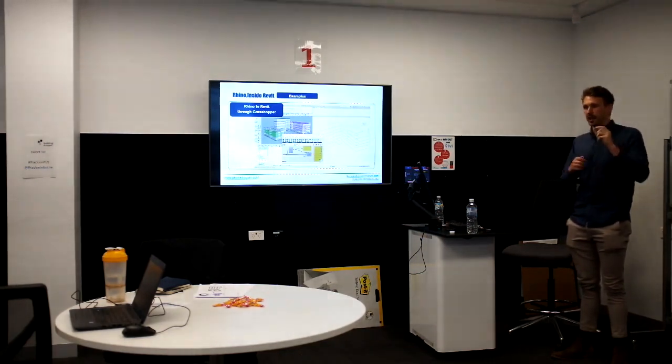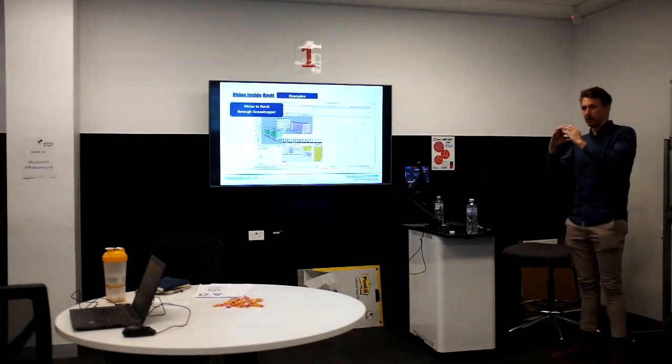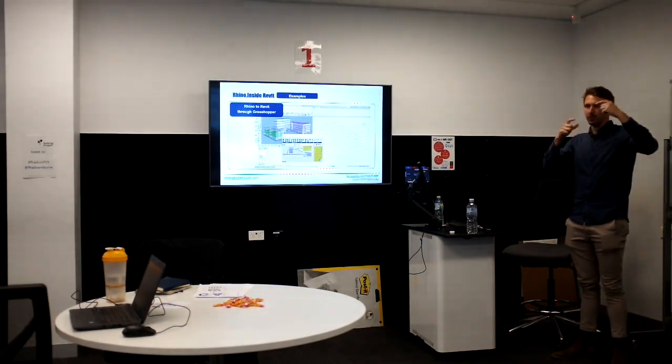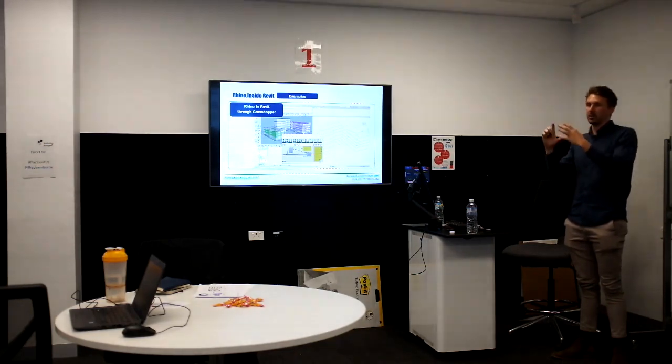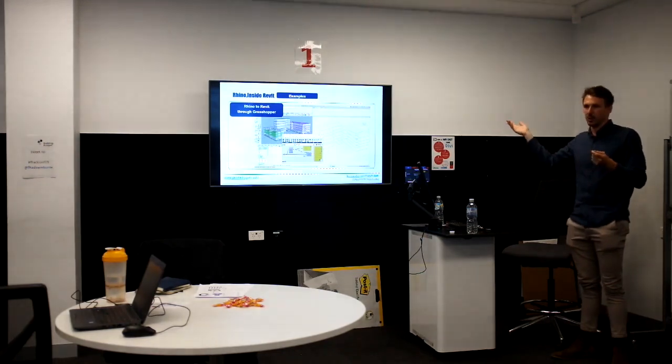We actually build a structural analysis database in Grasshopper, but it'll be based off, say, Rhino lines. We'll convert those lines and their properties to a structural analysis model, which we'll send to the structural analysis program through an API, or we'll generate a text file or whatever.